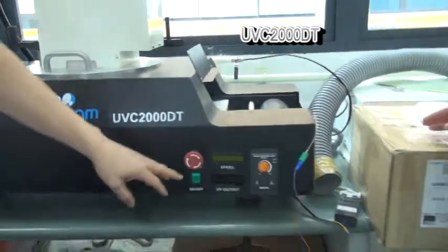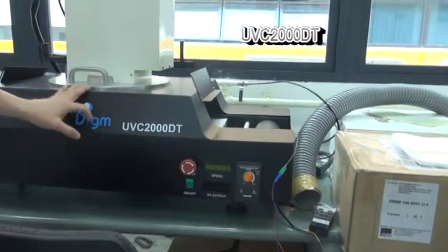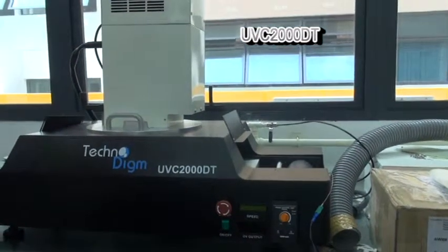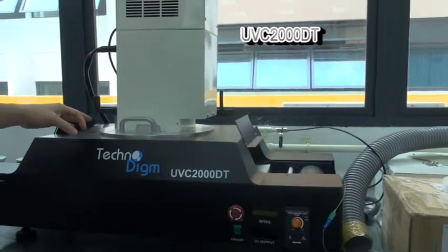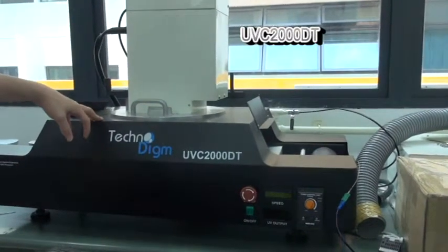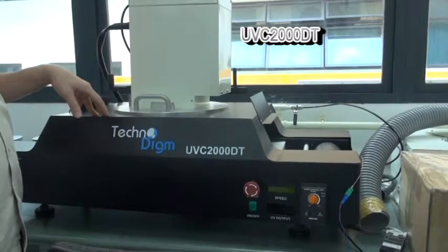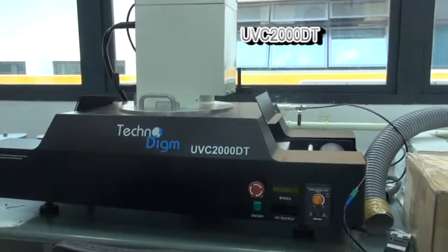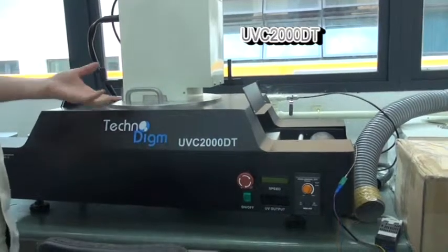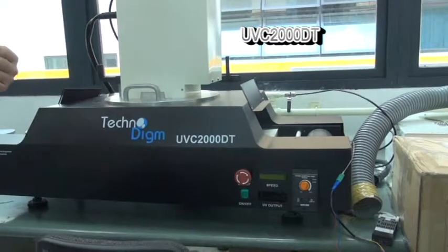So there's supposed to be a display here that shows you the UV output. But we found out that the electrical component we use is affected very much by the heat generated. So the value that comes out is not right. The sensor is okay, but the value is not right. So we take it out, and one of the guys is now redesigning the component to be away from the sensor. We're going to mount the sensor here, but the electronic components will be further away, so it's not affected by the heat.